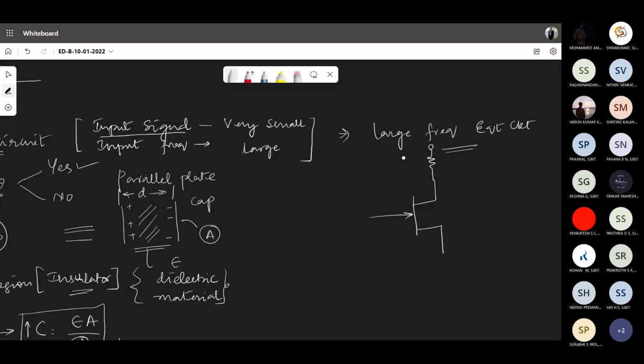I'm writing the amplifier circuit for you. Let us say I'm feeding around 20 volts here. The source is grounded. We are taking the output here. And then the capacitance, which we call the coupling capacitor. And let me connect the resistance here. It's around 1 mega ohm, let us say. And there is a coupling capacitor on the input side, CC1. And I'm feeding the actual input signal which needs to be amplified, VN, let us say. Now this input you're feeding, which has to get amplified by this amplifier, the signal voltage is very small. I can say voltage is around 10 millivolts peak to peak.